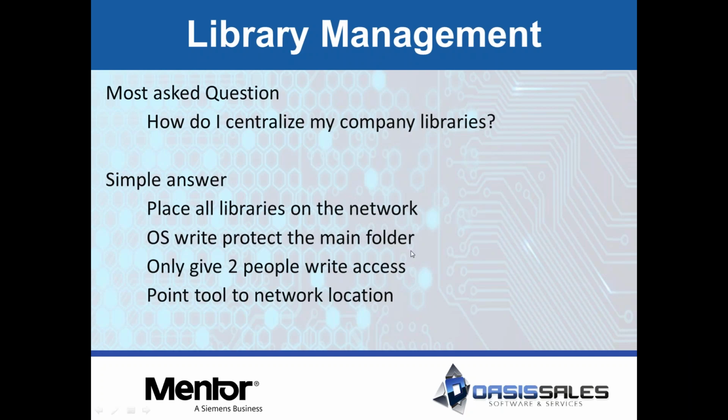So library management, one of the biggest questions I always get from customers when I'm visiting them or when they're just starting to use the tool, is how do I centralize my libraries? Or they've been using a tool for a while and they decide, I want to make my libraries more centralized. Well, what a lot of people don't really understand is that a centralized library is really just putting something out on the network and sharing it and protecting the folder where that information is stored so that not everybody in the company has access to it. Okay, that's really all a centralized library is.